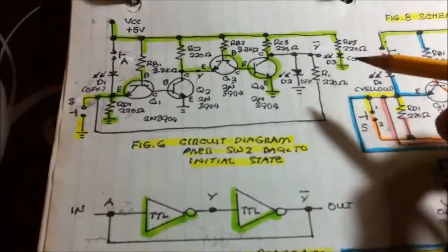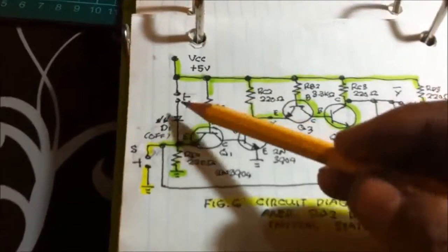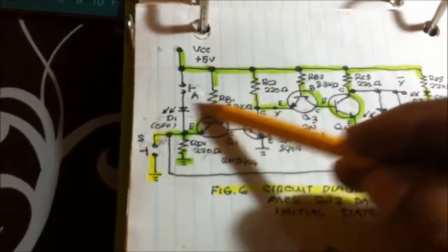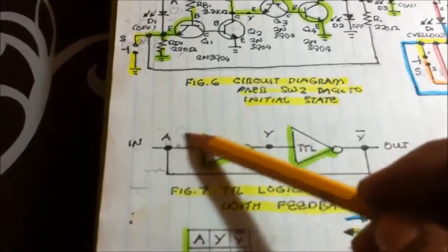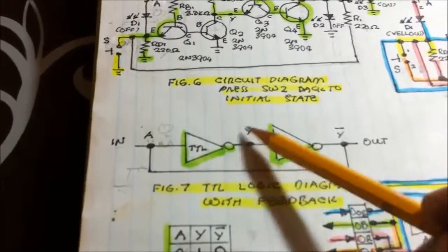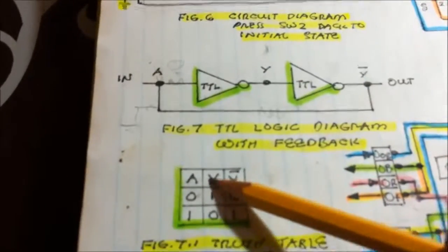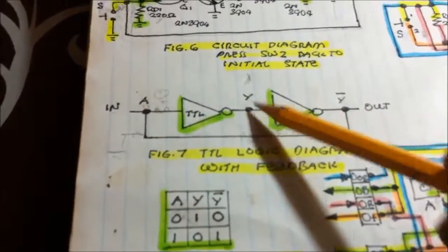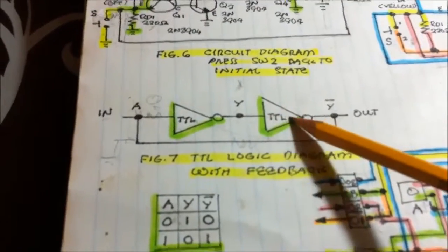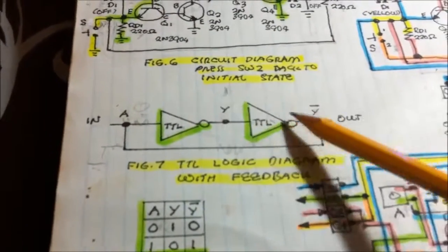That is my terminology. So when the switch is 0, or grounded, this is 0, the inverter inverts, and the output now is 1. It is the input of the other inverter, 1, it inverts again, 0, so it becomes 0.